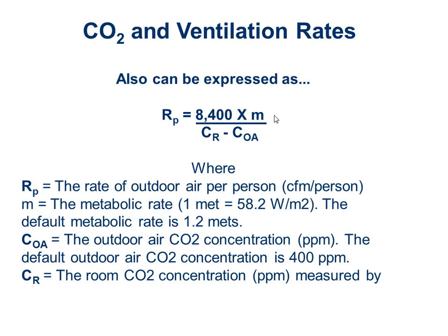If I divide that by, let's say I want 17 CFM per person, that's 592, and I add 400 for my outside air, assuming I have that right now. That tells me I need almost a 1,000 part per million set point for the indoor, for this particular space.